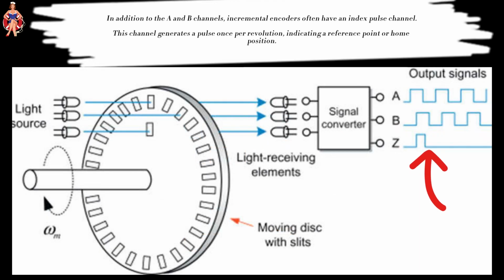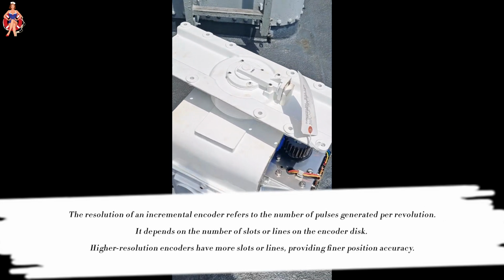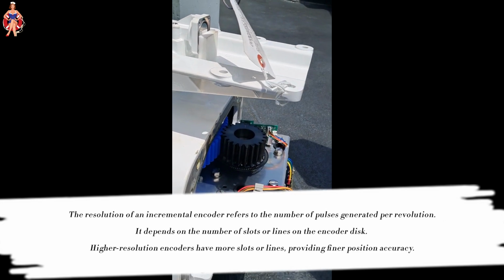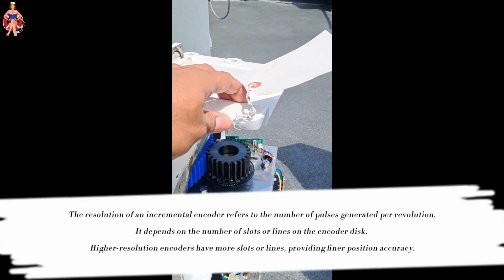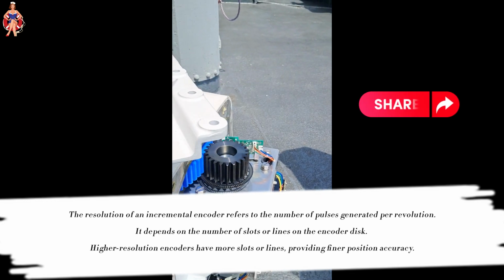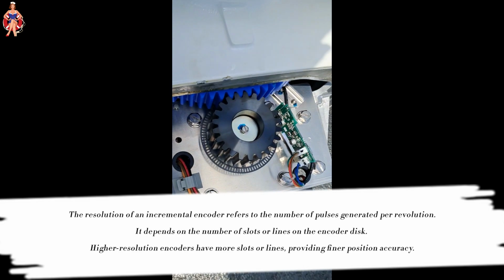In addition to the A and B channels, incremental encoders often have an index pulse channel. This channel generates a pulse once per revolution, indicating a reference point or home position. The resolution of an incremental encoder refers to the number of pulses generated per revolution. It depends on the number of slots or lines on the encoder disk. Higher resolution encoders have more slots or lines, providing finer position accuracy.